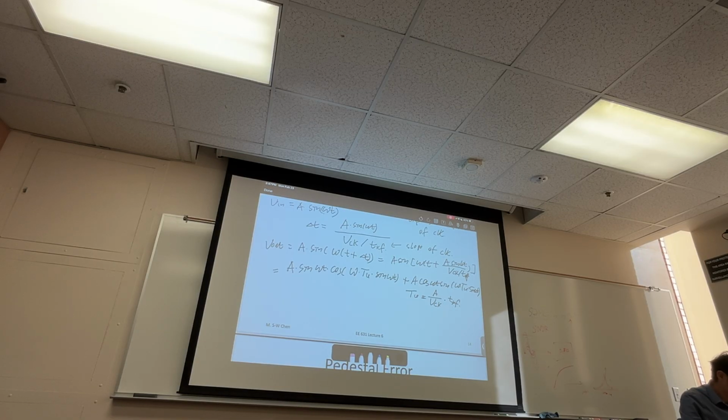And then you want this TRF to be very small, right? The clock rise fall time is relatively small. So theta in the end of the day will be a small number. So this argument here would be small. Okay, I want this to be small. So cosine theta, when theta is very close to 0, what is the value? 1.